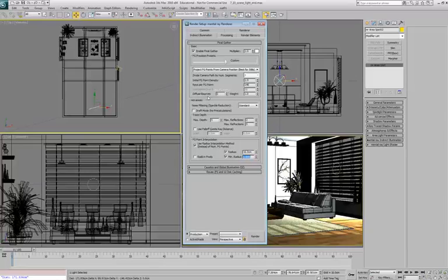With the diffuse bounce, we really don't need this to bounce around inside the scene. We don't have to worry about the weighting on it. If we were using final gather as more of the final render, then we're going to want to bounce the light around a little bit more if you're trying to brighten up the scene and push the color around the scene. Below that, we've got our advanced options, and our standard is going to work high. If we get noise inside the scene or little light spots, bright white spots here and there, then we can use that noise filtering to clean some of that up.